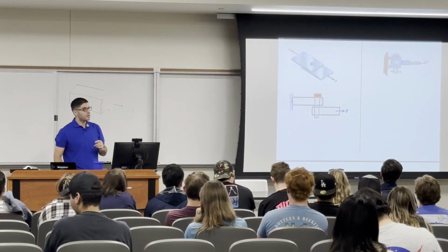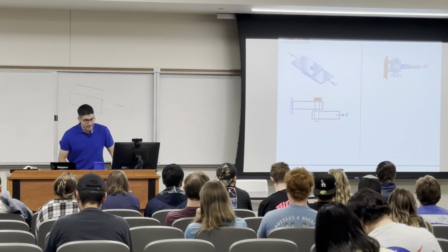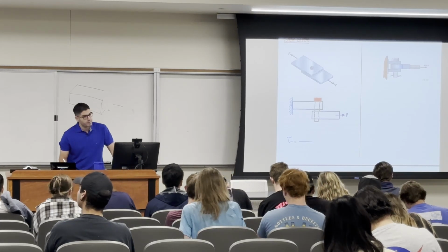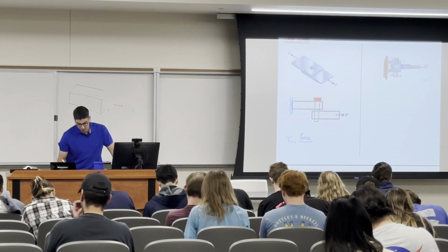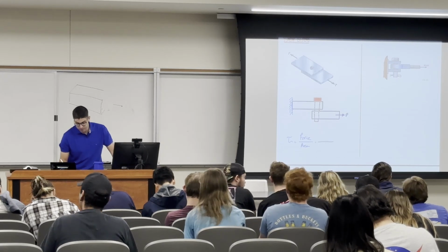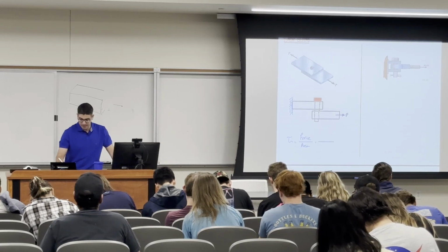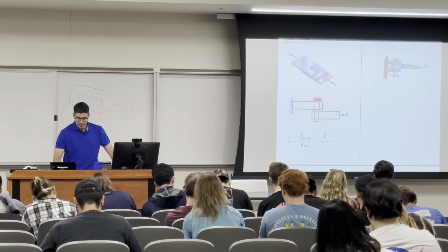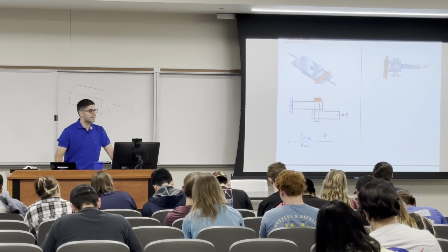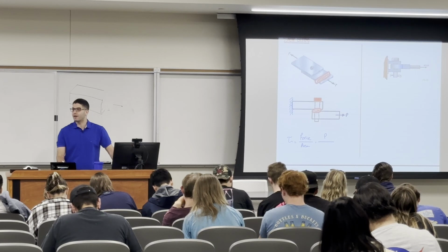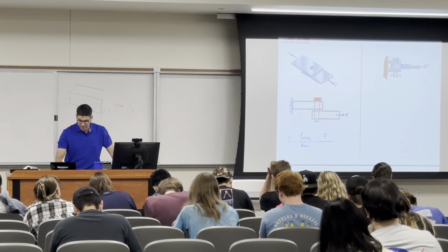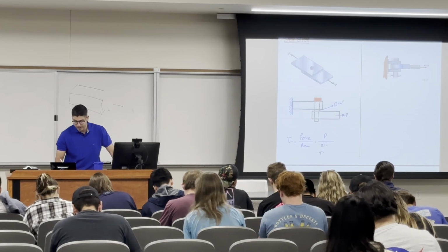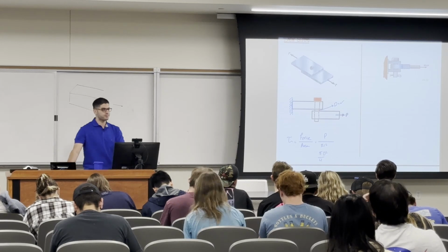Now, if I want to write the equation for the shear stress, we don't say sigma, we say tau. And this is for shear. And the same equation, it is force over area. But the thing is, which area? The force is going to be the same. It is wrong that if you want to calculate a shear stress, you will take, for example, the area of the plate. Instead, you should take the area of the pin or of the bolt, which is, if I gave you the diameter, either pi r squared or pi d squared over 4. Okay?